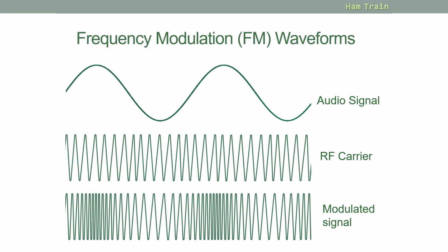If we look at frequency modulation, you'll see the same principle but slightly different. So again, here is our signal. This could be some speech. The carrier is the same for AM and FM. And what's happened here is as the signal reaches its height, you will see the frequency between the waves, so the number of waves you get per second, will tighten.